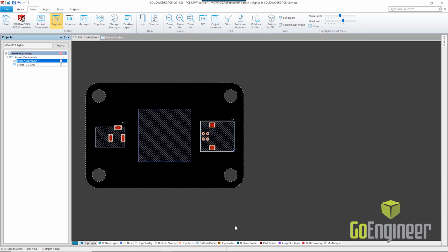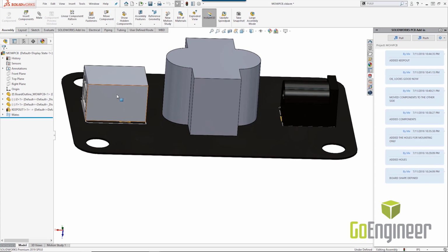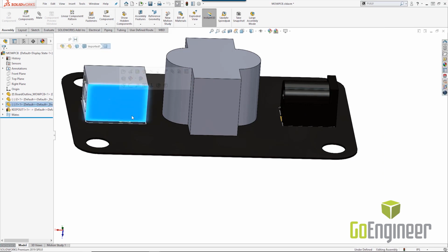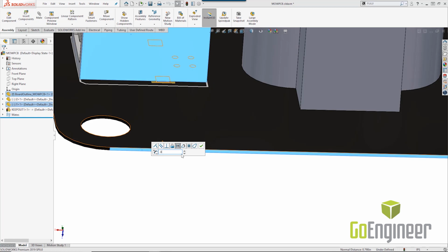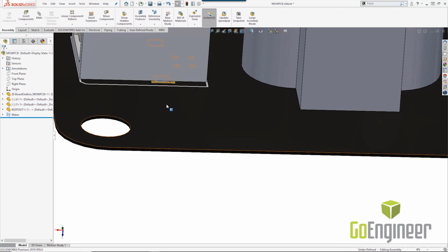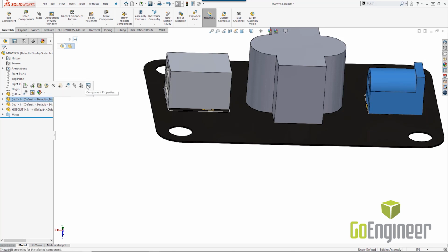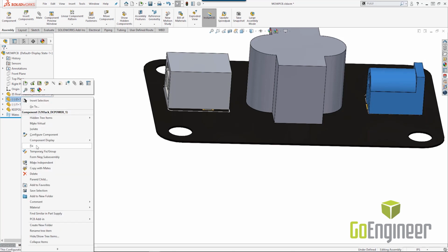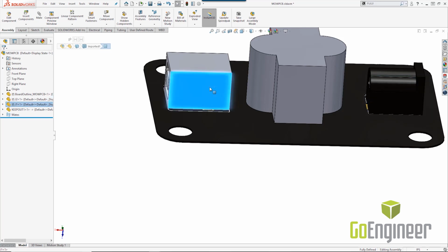And another new feature here is right now I'm actually able to move these components around. And as a SolidWorks user, I may have gone in and added some mate information to say this is the exact location. Maybe place some mates in here to say this has a specific distance of 0.8. So we'll leave that there. But once I get in there and do this, I don't want the SolidWorks PCB user to make any change to this, even if it's by accident. So one of the things I can do inside of SolidWorks 2019 now is go to that component properties, right click on it and select this fix command. So that's going to fix it here inside of SolidWorks. So I can't click on that and move it.